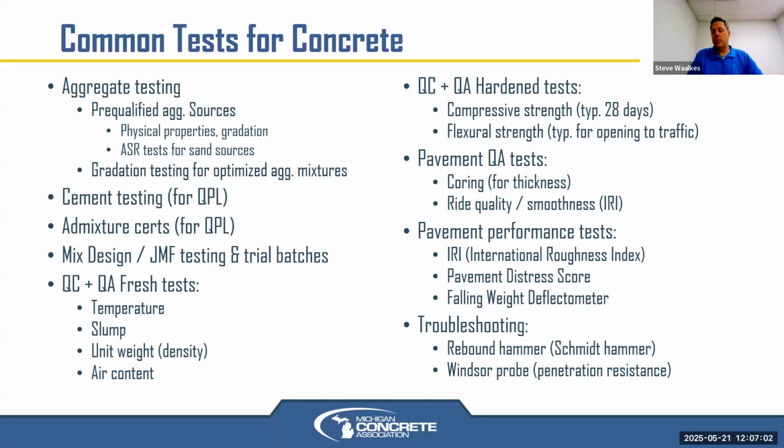The sand sources require ASR tests now under MDOT specifications. So we make sure that the sand is non-reactive with the alkalis coming from the cement. Yeah, there's a lot of testing that's done on the basic materials.